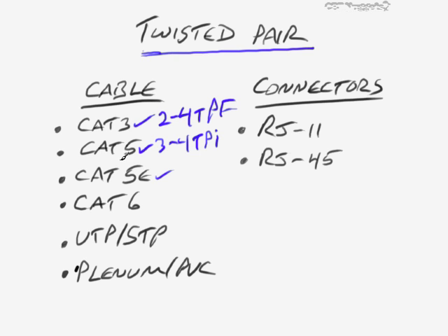You can use gigabit Ethernet on either CAT 5 or CAT 5e as well as CAT 6. Okay, it works on all three of those. But the latter two here are much more reliable for gigabit E, and so that's the preference if you're using that. And they all use 3 to 4 twists per inch down through here.